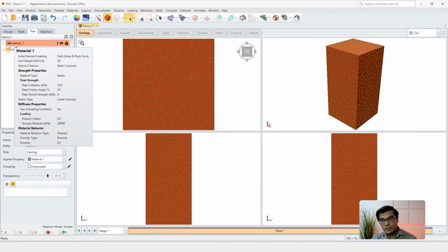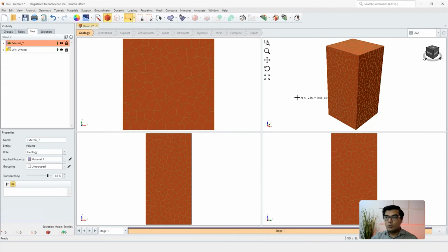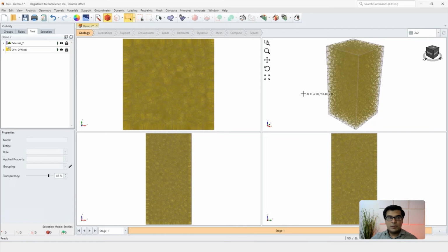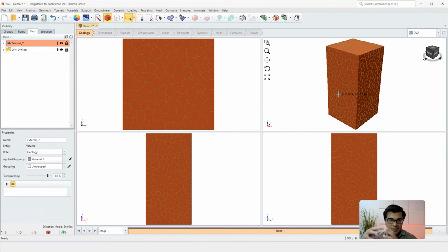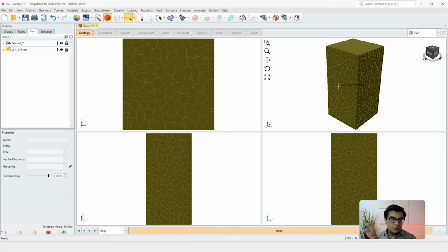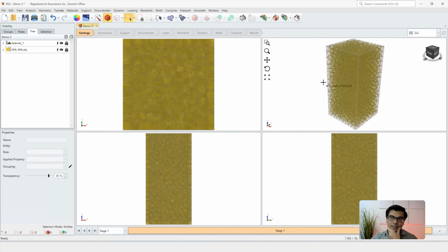If I was doing it independent of the DFN and doing the normal divide all, it would give me too many smaller volumes coming from the intersections of these small Voronoi surfaces. It would populate your visibility tree and affect the performance. It would be a lot harder, for example, to pick one side or surface of the external boundary.